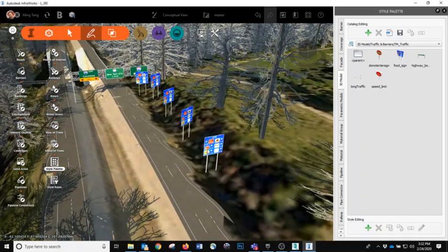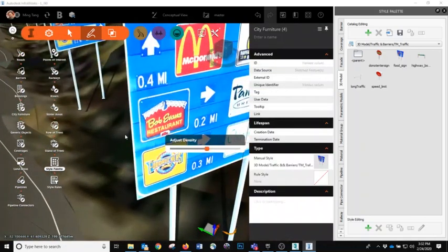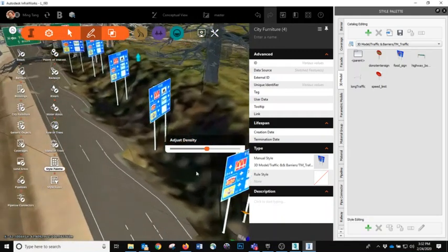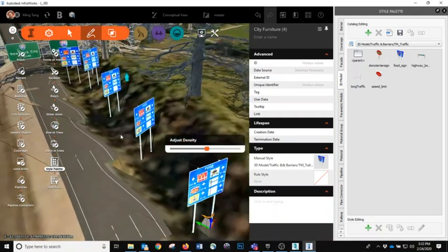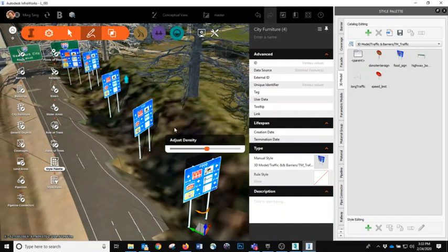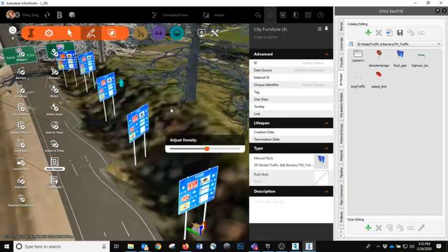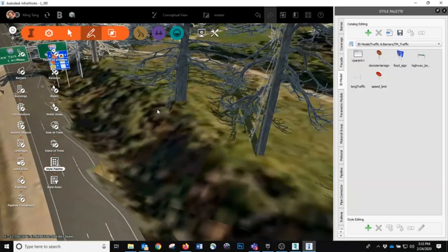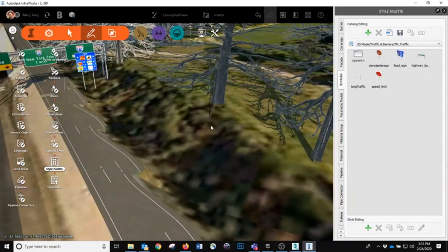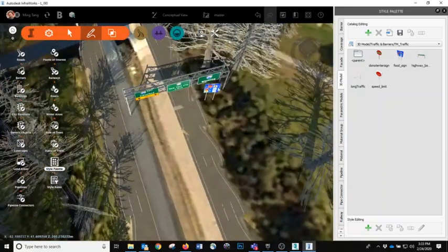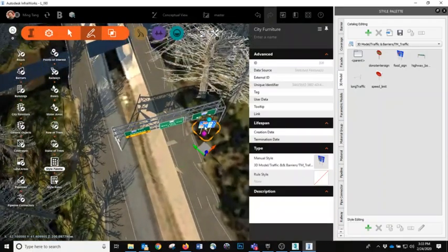Awesome. If you want to delete, this will be tricky. You have to double click first. So basically, you see the density control. You are basically selecting the entire row of the sign. Then you have to hold your left mouse button, move the thing a little bit. I don't know, it's a trick, and then you use delete. If you don't move the thing, it's somehow still thinking you want to control the density. It won't allow you to delete. Okay.